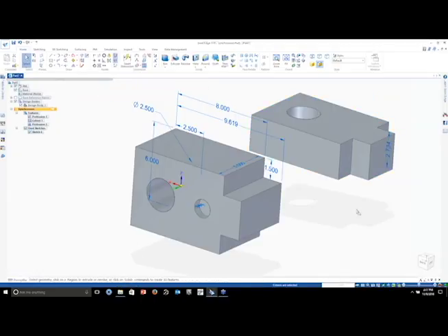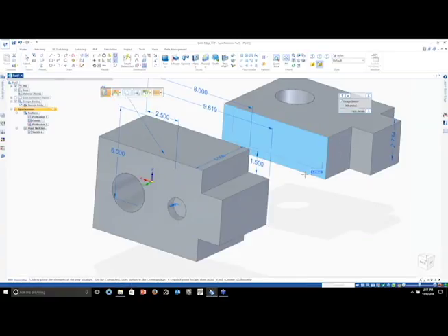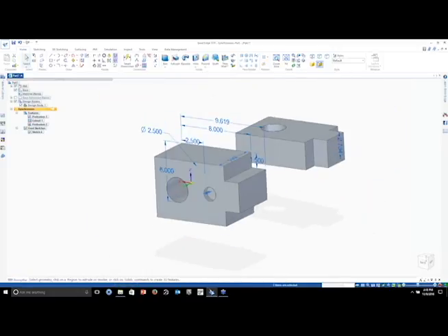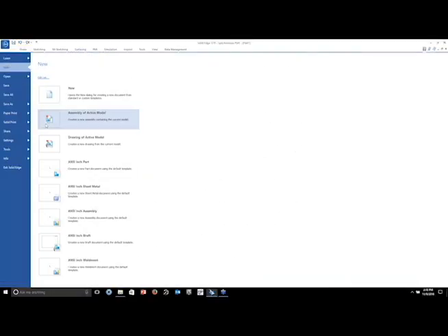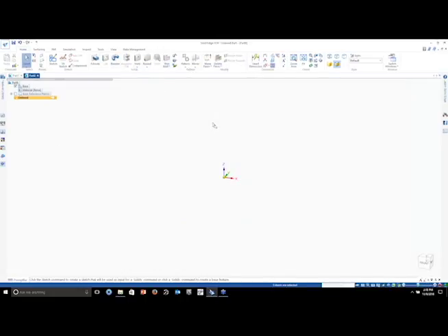Maybe I want to use it in a different orientation. So using my steering wheel, I can position it just centered here. And using Shift on my keyboard, holding it down and clicking that blue plane that I used earlier, I can change the orientation of it, and I can actually just rotate my sketch around. And now I can create another feature from that if I wanted to, and continue on restoring sketches. The sketch does not tie the geometry together, so even though they're from the same sketch, they are not the same width. All right, so that's using synchronous sketches.